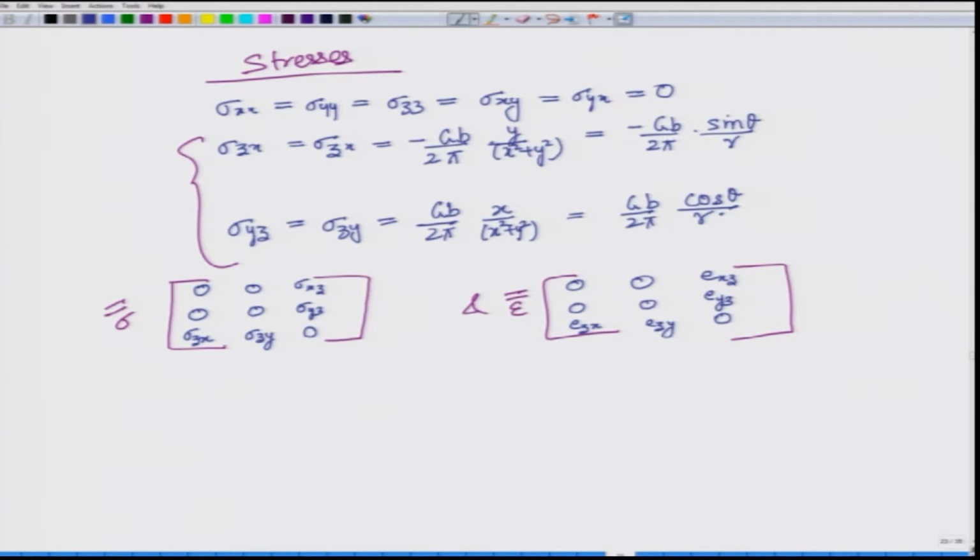So, what do we see? There are certain points that we can note down from here. The 0 components that we looked at over there are actually the tensile and compressive ones. So, there are no tensile or compressive components; the diagonal terms of the matrix represent the normal stresses, tensile or compressive.